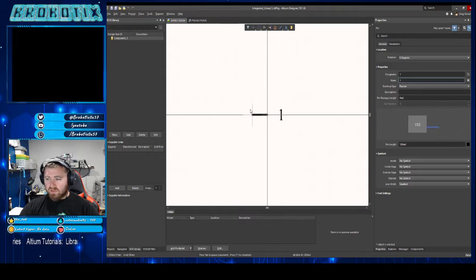up well afterwards. I generally do 100 mils, which you can see down here. So I use 100 mils for most of my pin spacing and everything, and then sometimes I'll do different spacing for like drawing the shape when it doesn't matter. But my pins are always on 100 mil grids just to make the wiring easier.